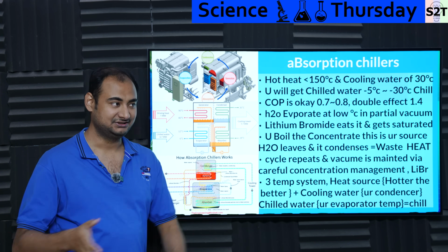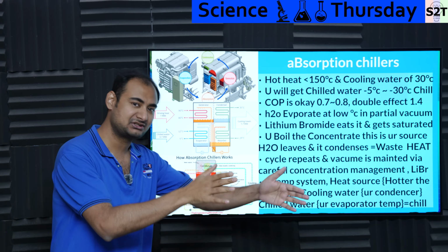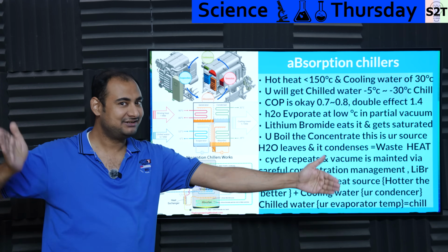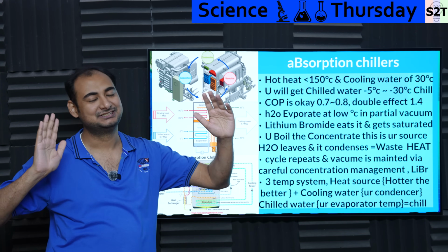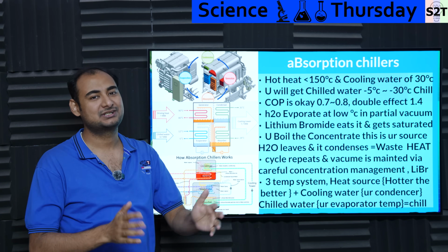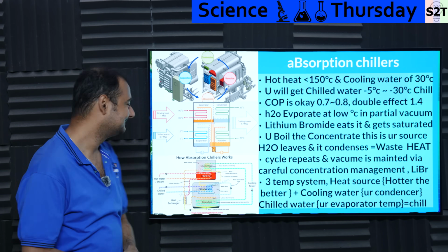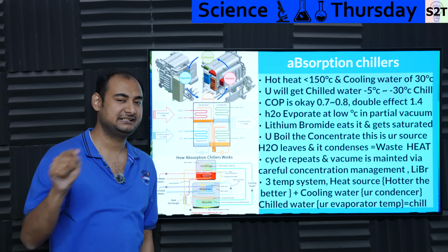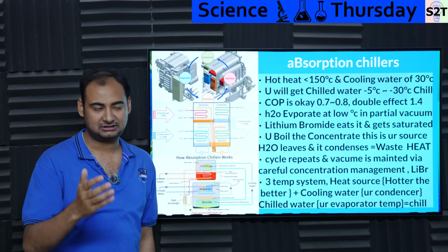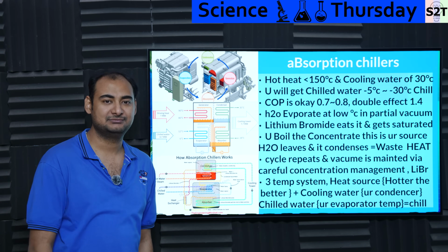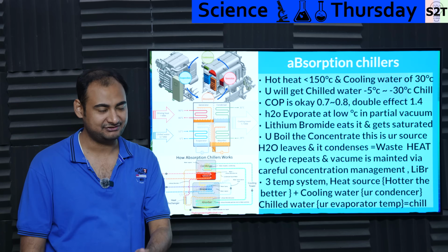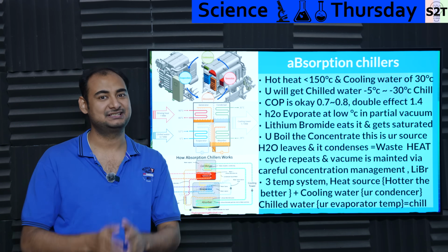It's not ideal. You have so much waste heat, even if the coefficient of performance is low, because you have 70% compared to your electrical system. Why not use that? Even at lower COP, it makes more sense, more direct. So that's what we call combined heat and power, or cooling and power. At that point, instead of 30-35% efficiency, useful efficiency goes to 60%.